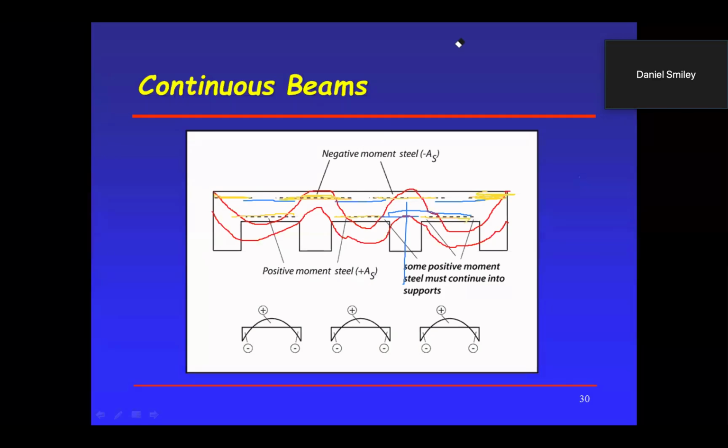Professor? Yes. Just real quick, why did we need reinforcing steel again at the end of the supports? Yes. In real life, when you put a beam and a column, or let's say this is beam and this is beam, you put them monolithic together, so the concrete forms a fixed connection.